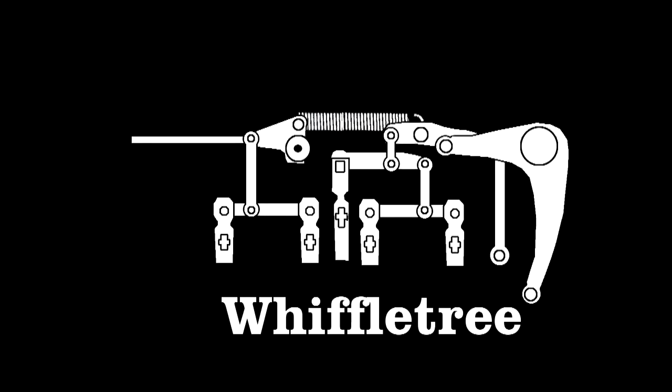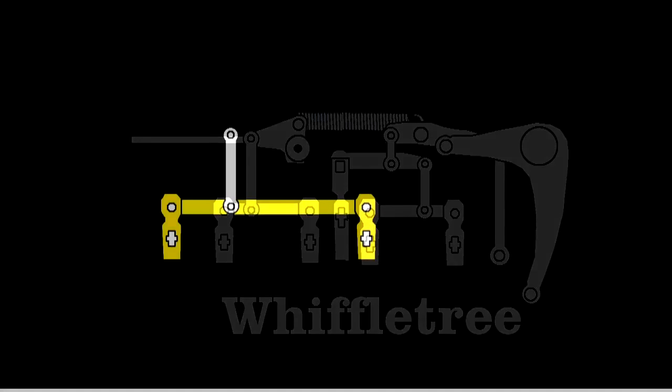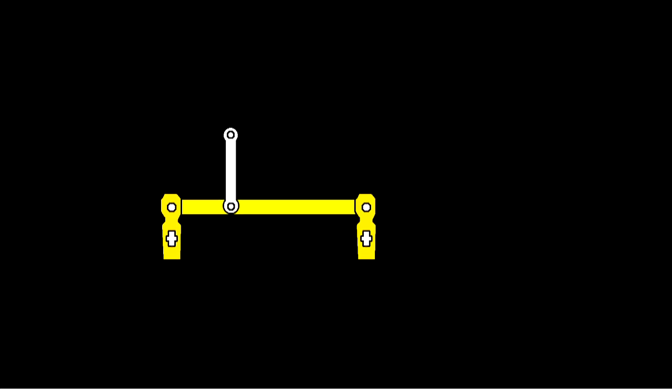The Selectric Whiffletree encodes some 7 bits of information, but to see how one works, let's look at the simplest converter, one that encodes 2 bits of information. A Whiffletree consists of rigid metal bars which are joined with pivots. What it does is the following. It converts a uniform pull on the vertical yellow tabs to 4 different positions of this blue bar. At the end of the blue bar might be a printhead, for example, that has 4 different characters on it.